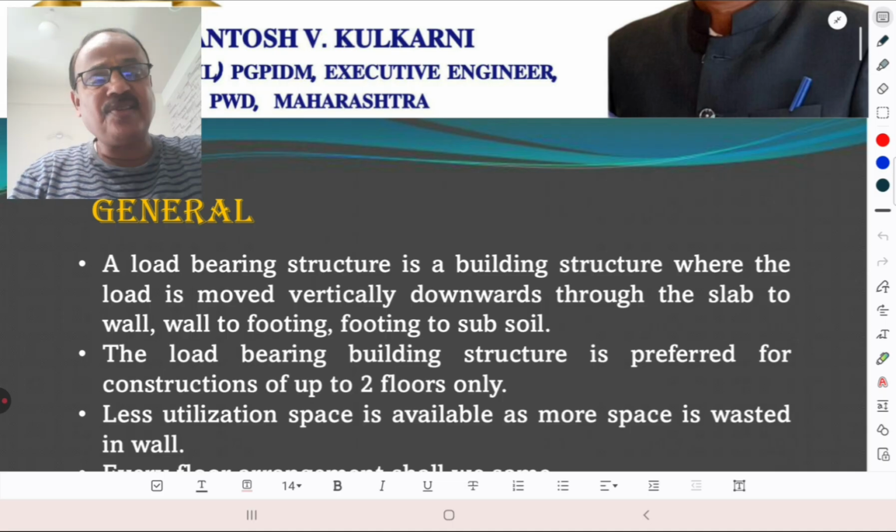A load bearing structure is a building structure where the load is moved vertically downwards through the slab to the walls, walls to the footing, and footing to the subsoil.